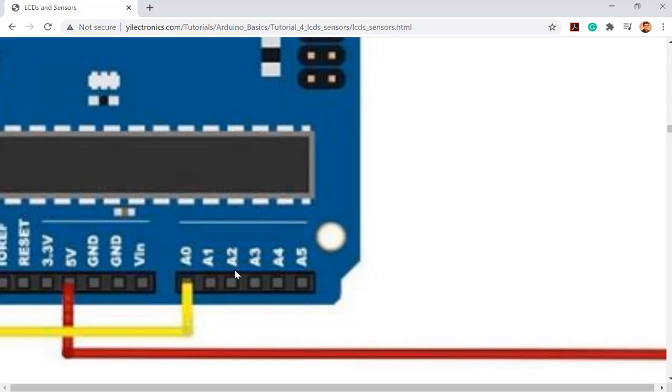So this microcontroller has an embedded analog to digital converter inside and has 6 channels, right? So every single channel can be used to convert analog signal input to a digital signal inside the microcontroller. And you can store that digital data, which is in a 1 byte form, to a variable, any variable, and then resend it to somewhere else, right?